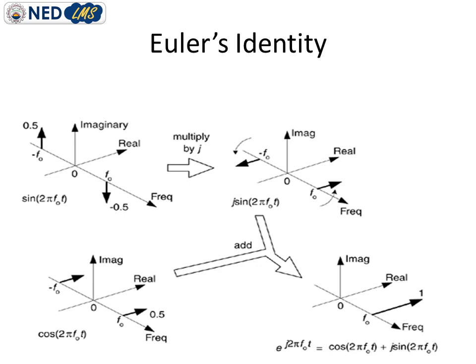So you can see that we finally have the spectral line present only on the positive f naught and the magnitude is 1. So you have observed how interestingly the Euler's identity actually converts cosine signal into frequency domain, and again these two frequency domain representations are added up to get the frequency domain representation of complex exponential signal.